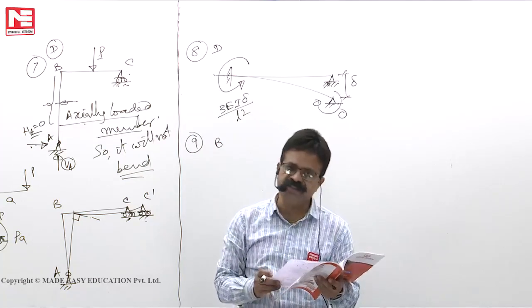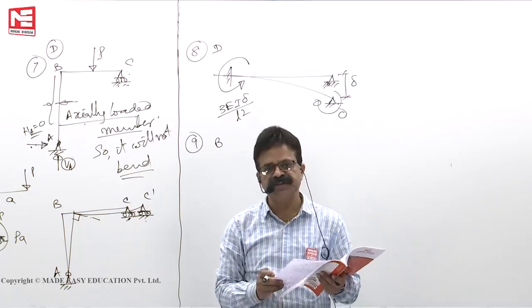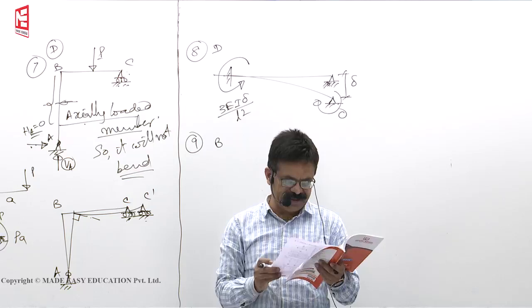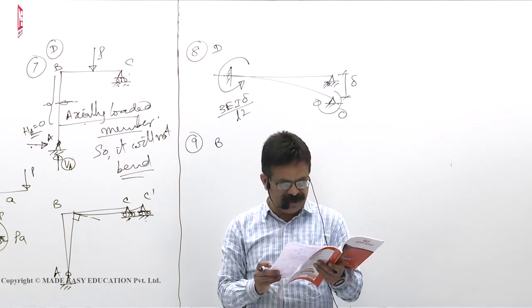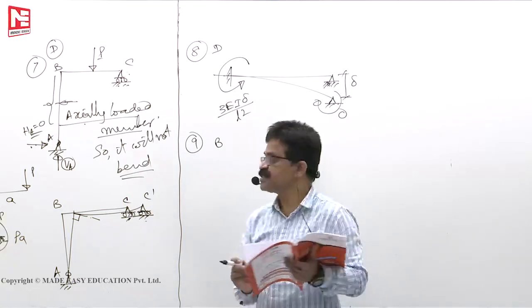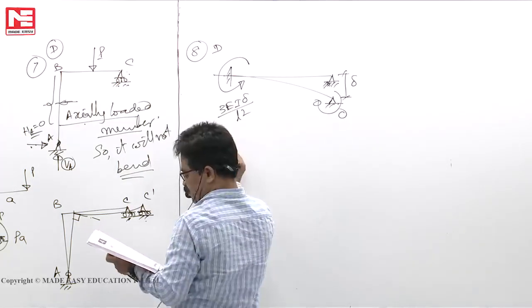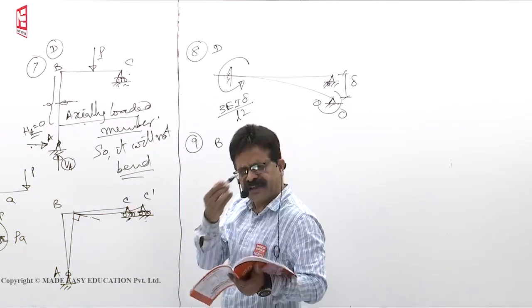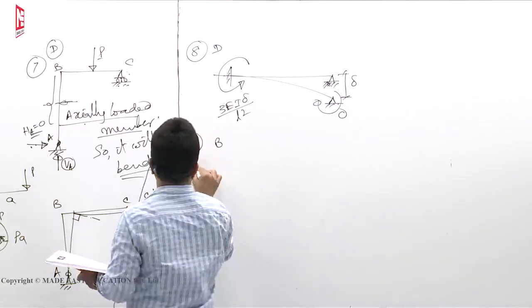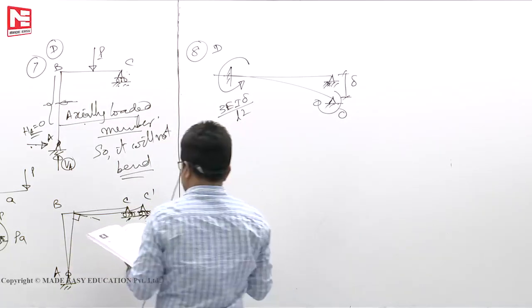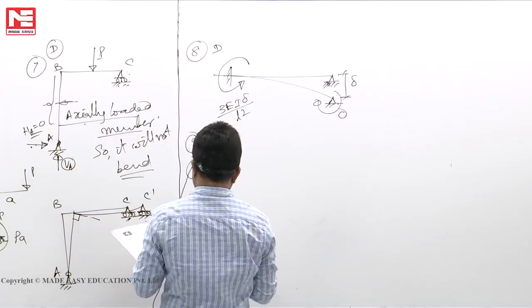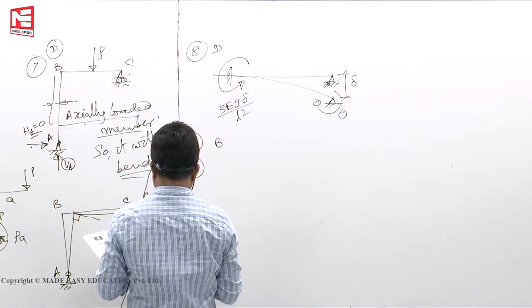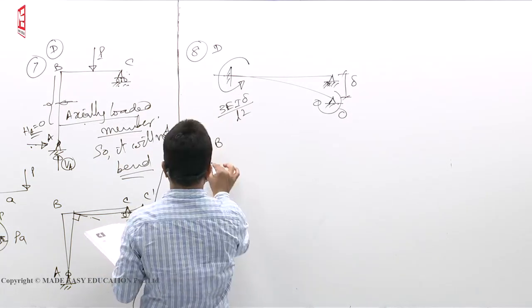Substitute frame method means an approximate method of moment distribution for the frames. Okay, not applicable means correct. Next, so the wrong answer is this one, because once you know the wrong answer, pick up the other three statements, whatever they are, don't worry. Next, 10th question. Carry over factor CAB, we solved in the class. CAB, we got it as 1.